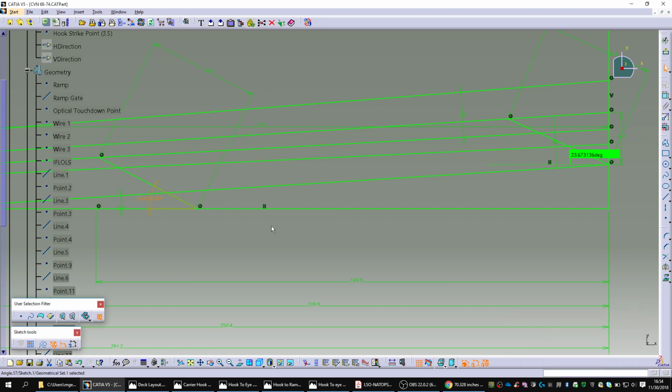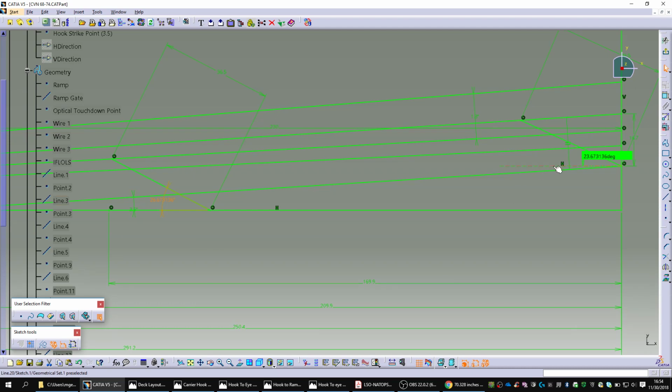I get that a lot of these don't really matter. I work in fractions of inches every day, so a thousandth matters to me. I just turn on more decimal places than needed sometimes, so I can know what that last figure is. Sometimes we get into lower points than that. Angle-wise, we usually hold plus or minus half a degree. It depends on what it is.